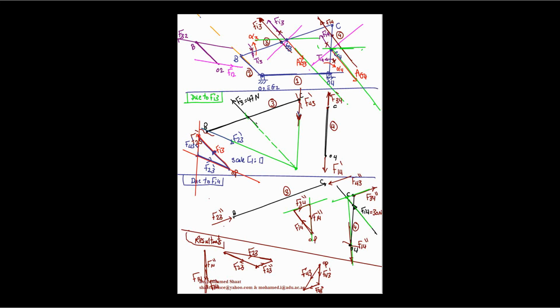Your objective is just to measure. Draw a line from this point. You're just gonna draw a line that is normal to both of them. This angle should be 90 degrees. Then you're just gonna measure this distance from this point to this point. This distance should be the h that we are talking about. You're just gonna measure this one and reverse the scale. Remember that we were using scale 1:1 for this graph, for this mechanism, right? So your objective is just to measure this h distance.